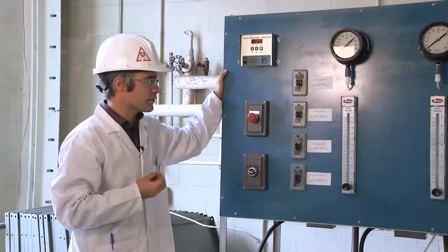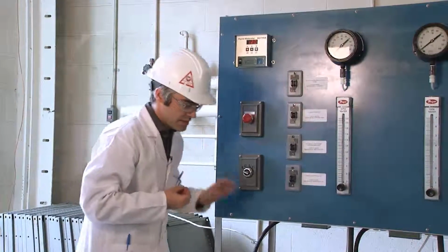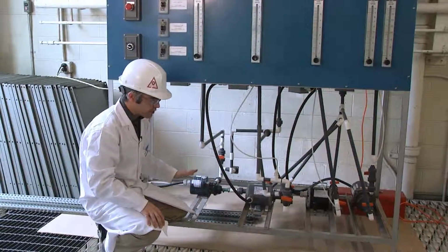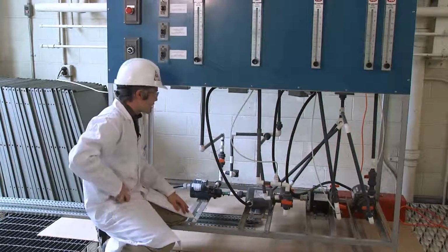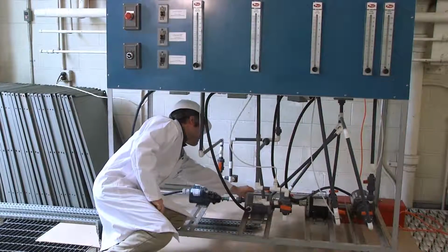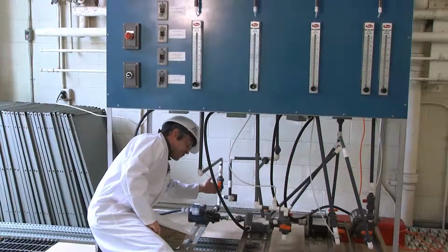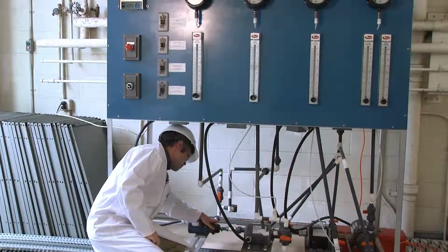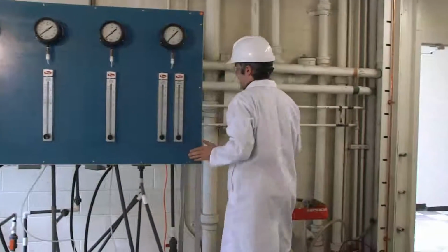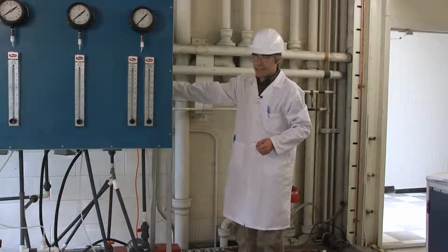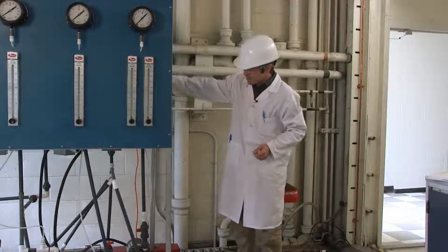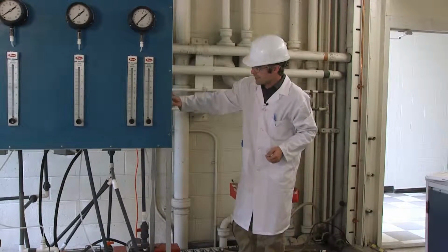In order to turn on the first pump, or any of the pumps, we must only operate one pump at a time. All of the valves will begin the laboratory in the off position. In order to activate the screw pump, we must turn on the inlet valve and the outlet valve. On each one of the pumps, the inlet and the outlet are directly connected closely to the pump. Secondly, we will check the reservoir of water located behind the apparatus, and we must make sure that the intake for the water is located below the water line within the reservoir.